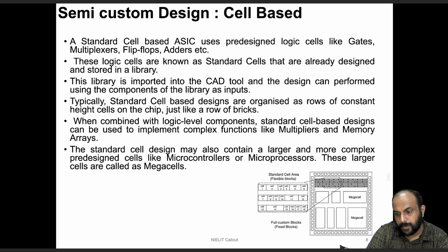Standard cell-based ASICs also use predefined logic cells like gates, multiplexers, flip-flops, adders, etc. These logic cells which are predefined or pre-designed are called standard cells. These standard cells are stored in the library of the CAD tool, and this library is imported into the CAD tool so the design can be performed.